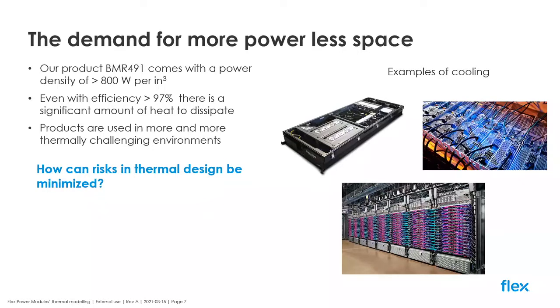Over the years, power density of the converters has increased more rapid than efficiency. More output power per volume unit, but also more heat to dissipate away per volume unit, which put a challenge on the cooling. At the same time, cooling temperatures are increasing. Expectations on high output power, even with a 100 degrees C base plate temperatures, are not uncommon in 5G applications. To the right, we have a few pictures showing applications with advanced thermal solutions. We have a trend in that customers start moving away from direct mounted heatsink and airflow.